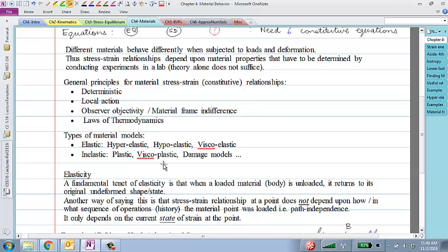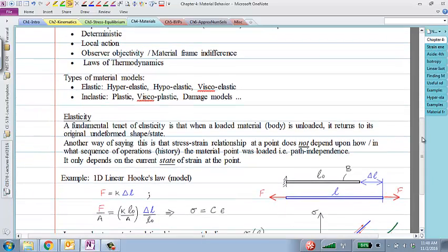If it is not viscoelastic, if it's just elastic, and if I drop that load on here, then it oscillates and goes to its steady state position, right? That steady state position is achieved, at least in the static sense, instantaneously. But in viscoelastic models, viscoplastic models, it takes time for them to happen.